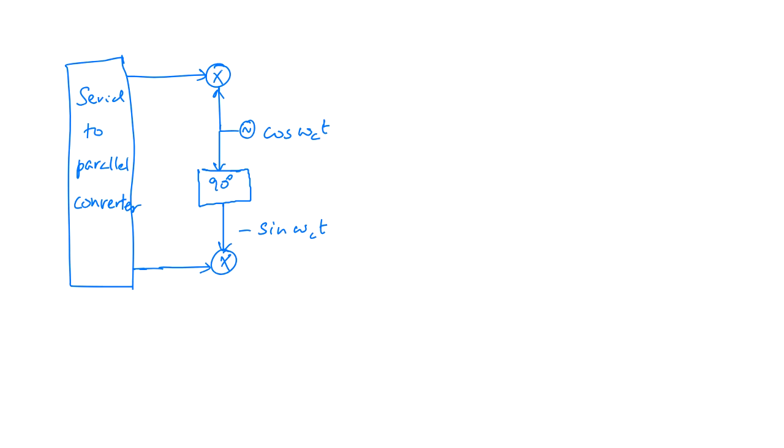Whatever information bit is coming in the sequence is divided into two parallel streams. The bits which are coming at say Rb bits per second, that's our information bits, are divided into two parallel streams, and the upper part of the information stream is going to modulate the cosine carrier, and the lower part is going to modulate the carrier which is 90 degrees phase shifted.